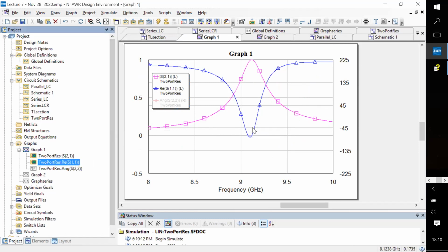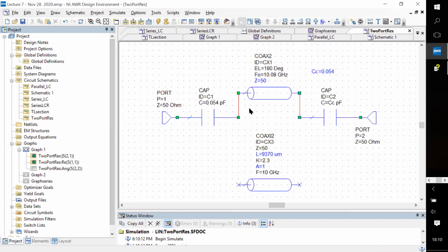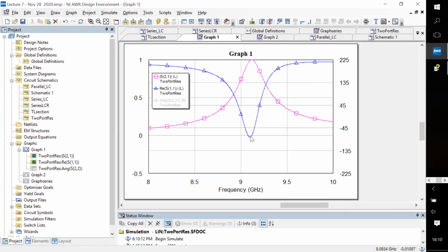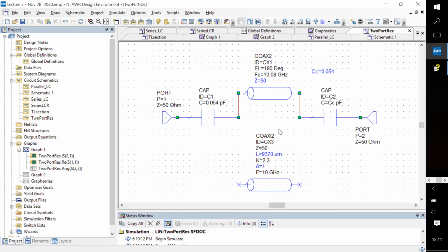This is basically a reflection now. Remember, just like you had a loss now, because it's from the point of view of the reflection from port 1, it looks like a lossy resonator. And remember that it's a critically coupled lossy resonator because it had basically 0 reflection. So that's why the real part basically goes close to 0. It should have actually been exactly 0, I guess. Did I introduce some, or maybe not? Let's see this.